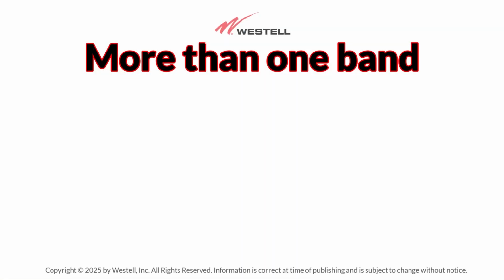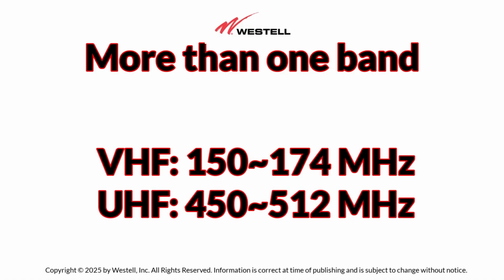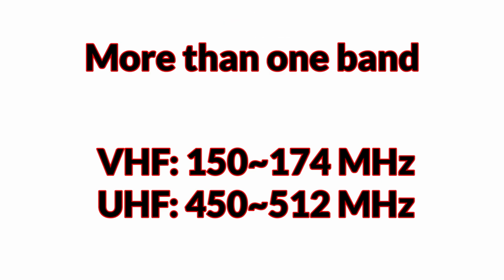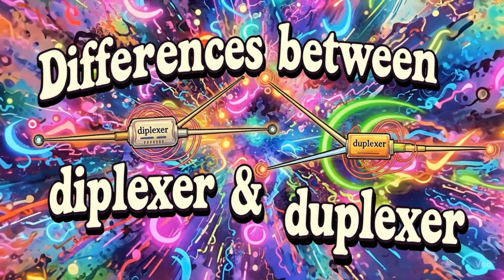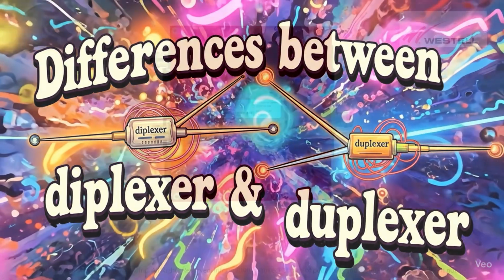In addition to the 800 MHz band, public safety networks can operate in the VHF and UHF bands. VHF ranges from 150 to 174 MHz, while UHF covers 450 to 512 MHz. Now, with that background established, we can identify the differences between a duplexer and a diplexer.